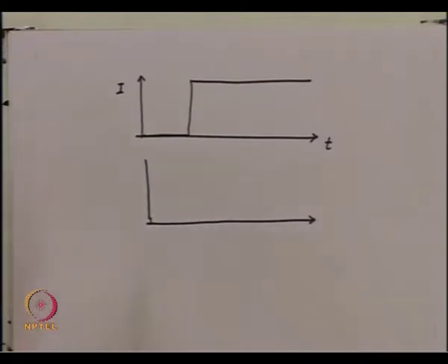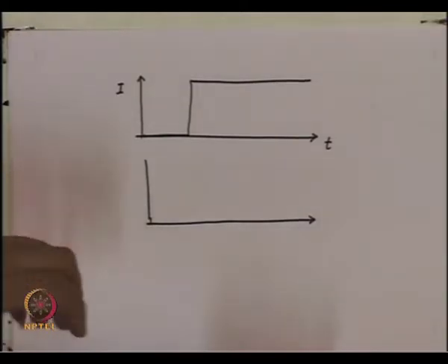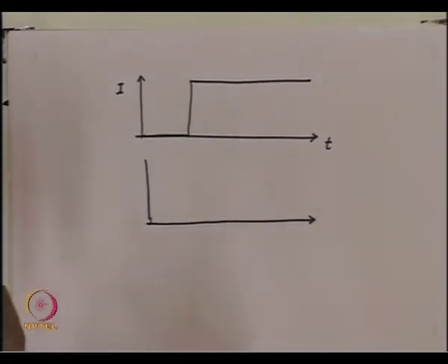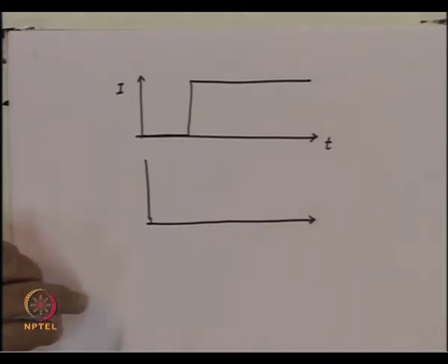Large numbers of electron holes will get recombined, and you will get essentially a pulse of light. But as soon as the stimulated process starts, the depletion region will be depleted of electron holes. So, the gain of the system will fall, and the stimulated output also will reduce.